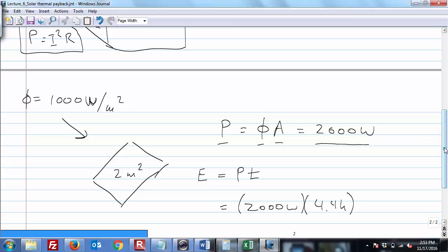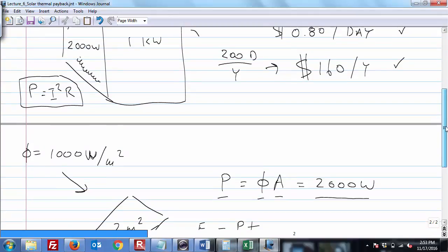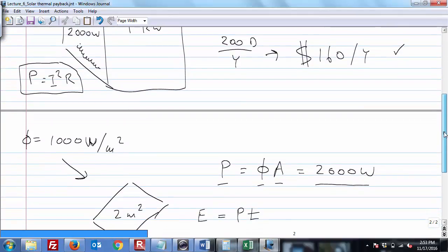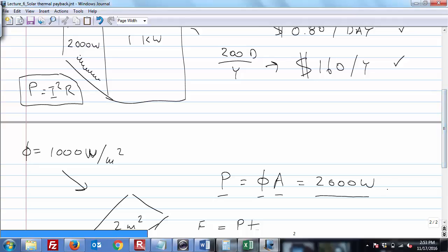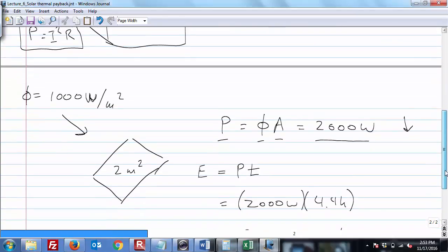You've made a solar heater that's the same power as the electric heater. In general, I would call this undersized because you're going to need some storage. So you might actually double that, triple that, and you might have some hot water storage elsewhere so you can bank that heat, so when the sun is not shining, you can draw from it.